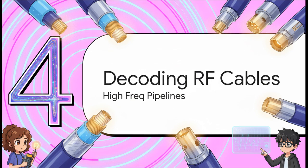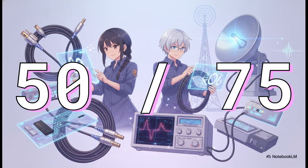Section 4. Decoding RF cables, high-frequency pipelines. Let's shift our focus to high-frequency radio frequency, or RF cables. These are the ones used for video, transmission lines, and antennas. In this world, you'll constantly see ratings of either 50 ohms or 75 ohms. Now, these numbers aren't just your standard resistance. They represent what's called characteristic impedance.